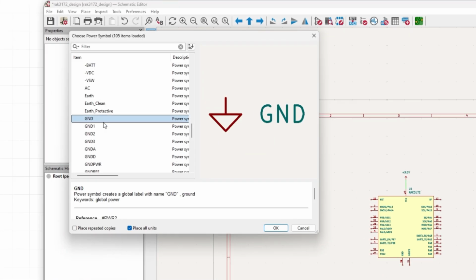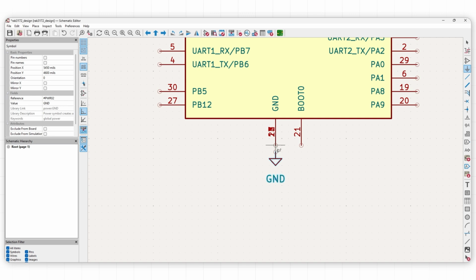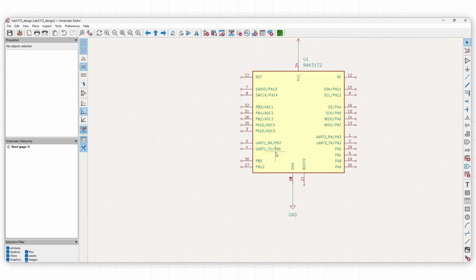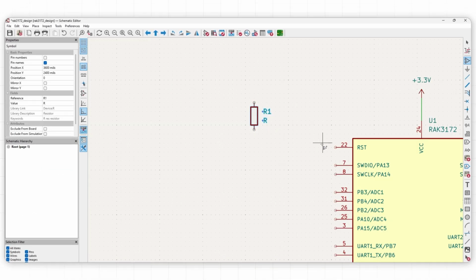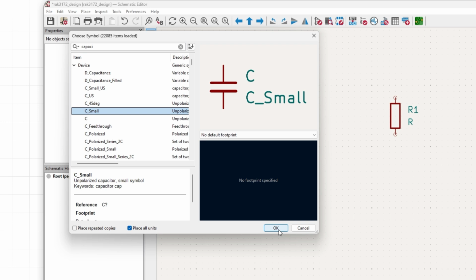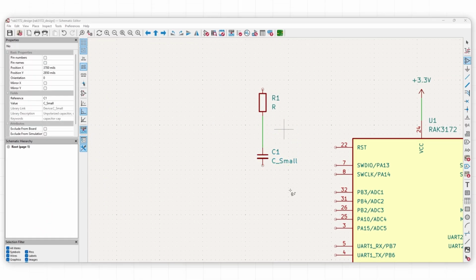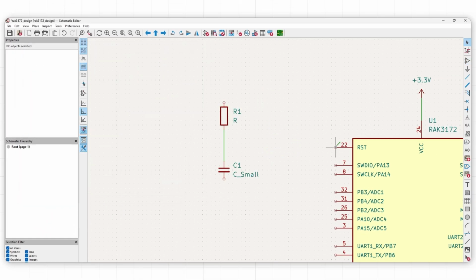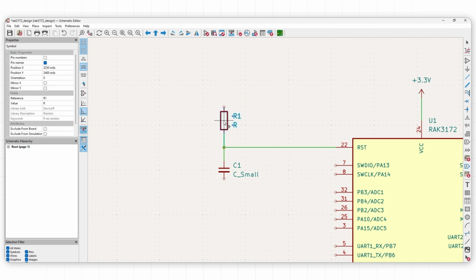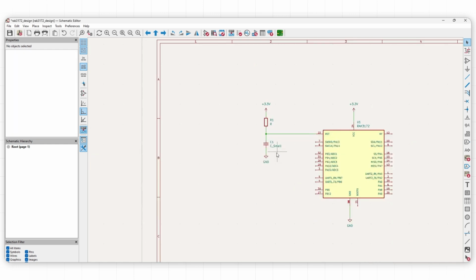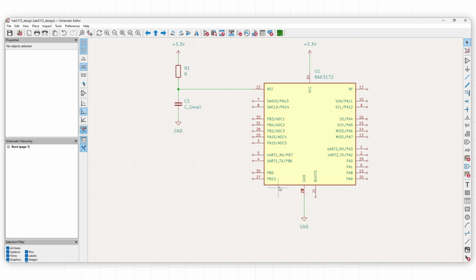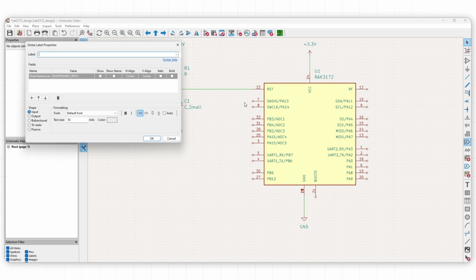We will explore the considerations to take note of when designing a custom LoRaWAN end device board for your IoT LPWAN applications. 1. Ensure that the reset pin has a bypass capacitor. The capacitor ensures that there is a stable signal on the reset pin. Without this capacitor, the RAK3172 will be susceptible to external influences which can cause unwanted resets. If the RAK3172 LoRaWAN module will be deployed in a noisy environment, you might need to add an extra capacitor on this pin with a different value to complement the resonant frequency of the 100 nanofarads that is commonly used.